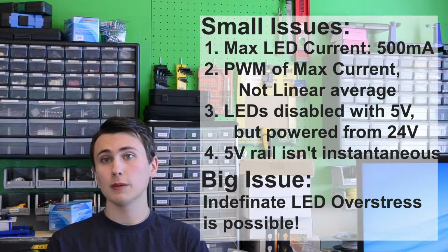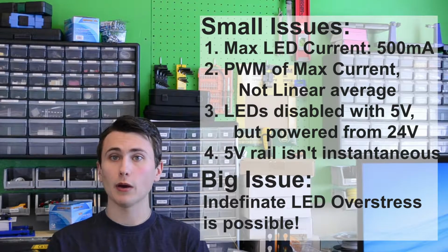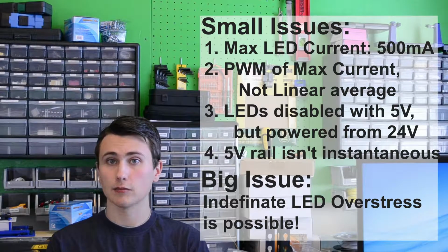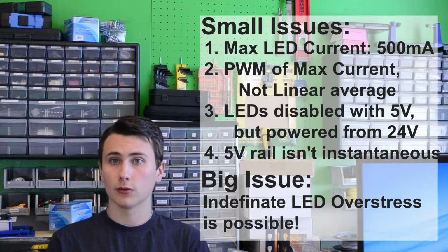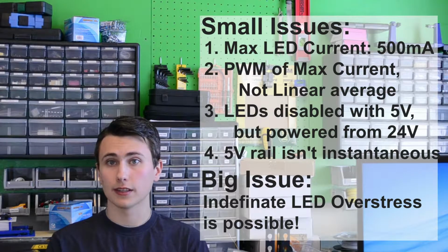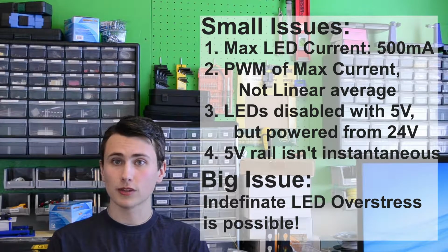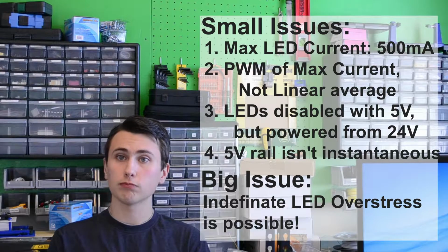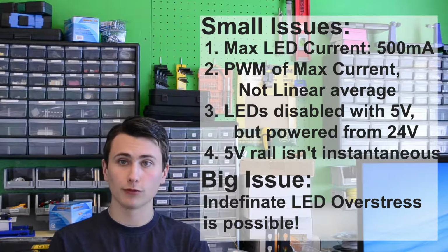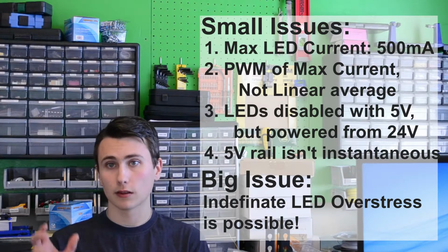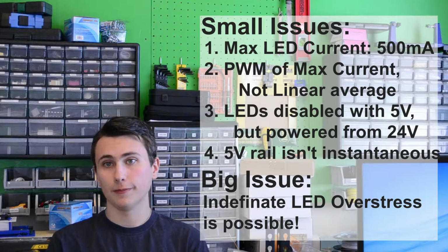This condition would typically only last for a few milliseconds during power-up, but we learned our lesson quickly when we plugged the 24 volt connector into the board and a couple of LED channels popped after flashing briefly. We didn't notice this critical design flaw right away, since we caught it before I received the PCB fabs. Once we noticed, we took care to always plug the barrel jack into the board first when the power supply was discharged, and then plug the power supply into the wall.